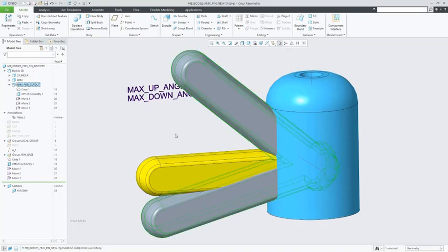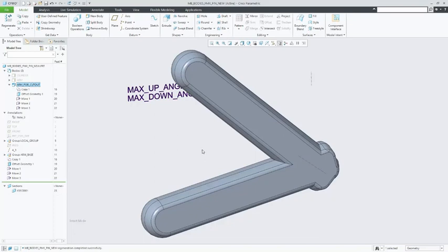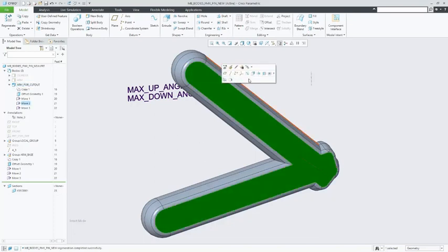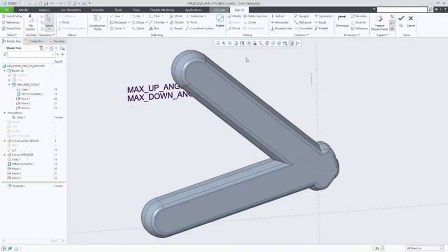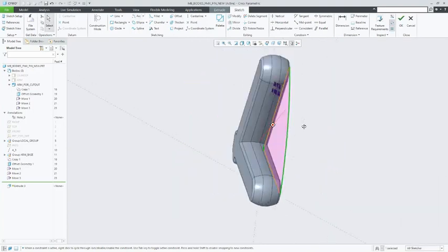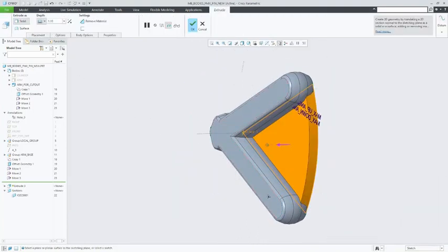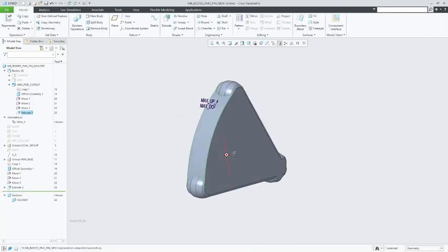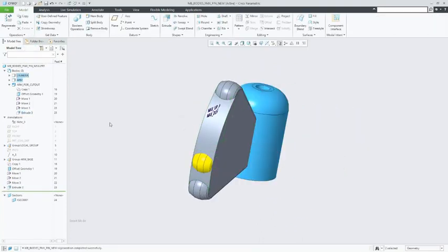We will fill the space between the gray arms with geometry to get to something that resembles and is close to somewhat like a motion envelope of our last move operation. So we made it the default body, isolated it from the rest, and now we create a sketch and extrude that will define geometry that fills the space and can serve to represent somewhat the motion envelope for that cutout. This now results in the body we can subtract from our cylinder.